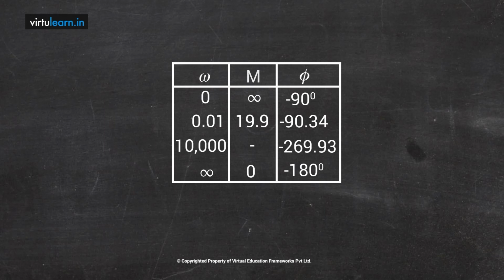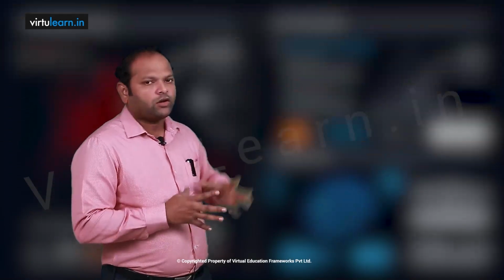So this is the table available for the given open loop transfer function GH(s) = k / (s(s+2)(s+10)). From the data in the table, we have −90° as the starting angle and −270° as the ending angle. Using this, we can draw the polar plot.